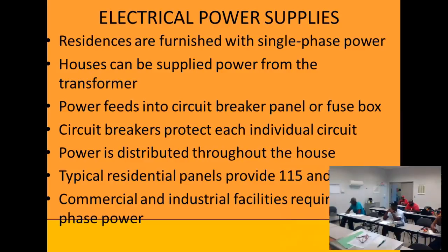It's a transformer, but it's a variable transformer, so we'll talk about transformers later anyway. So in the component class, what we would do is take, say, a relay that is rated at 24 volts on the coil. In other words, the magnet at 24 volts will pull in the coil, right? Close or open the contacts it's supposed to.